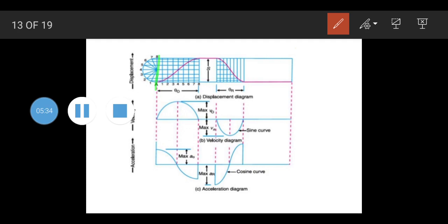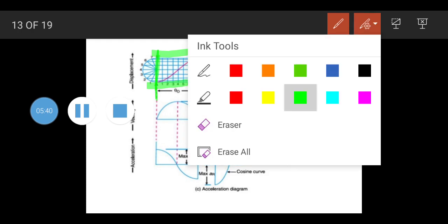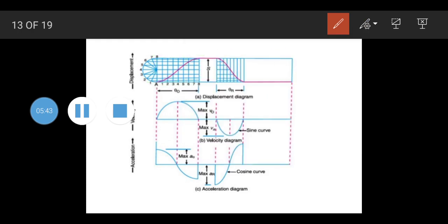We have to complete the rectangle, so this way we will be completing the rectangle. The height will depend on how much the lift of the stroke is. After that, we have to draw a semicircle which takes the lift as a diameter.